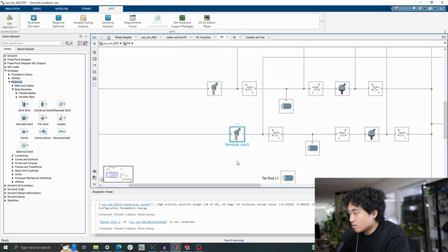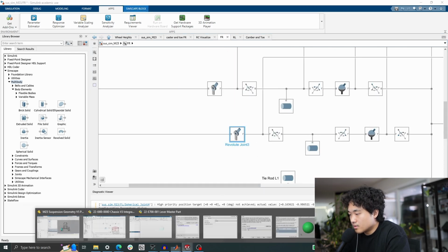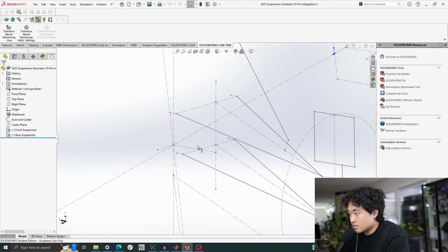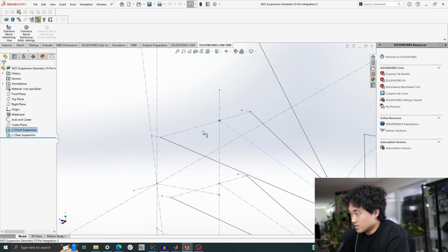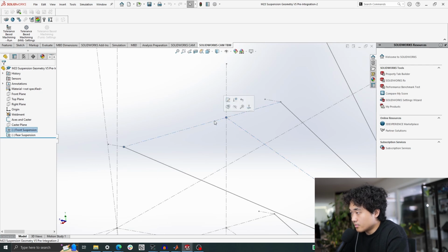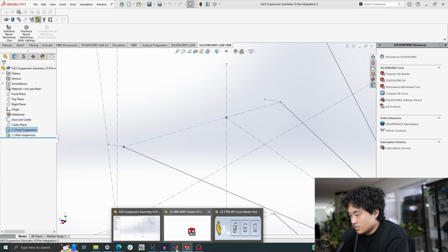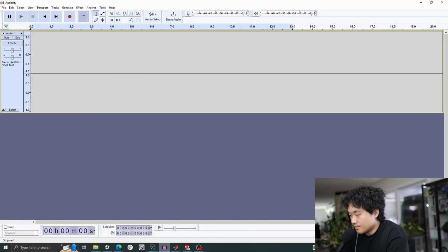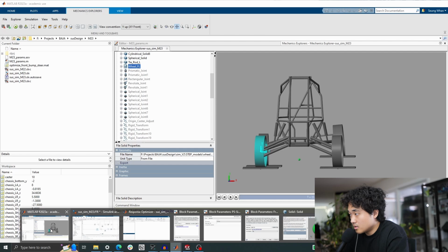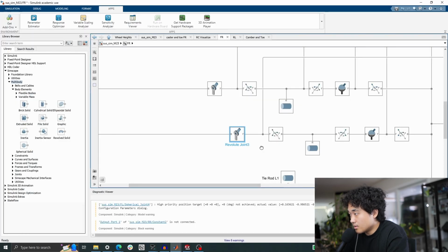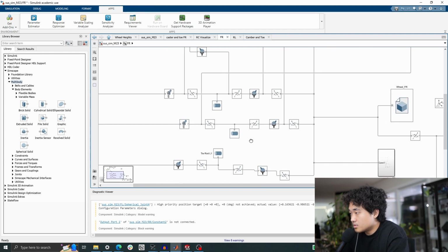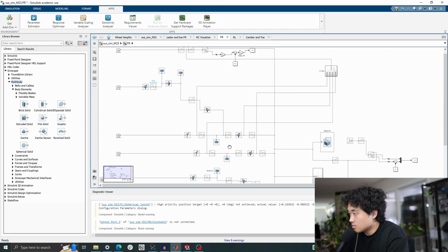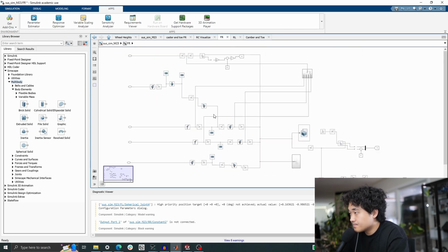For example, in real life, this is more like two spherical joints, right? So one here, but we're modeling just virtual A-arms for the sake of some simplicity. So we could just say along this line, it's a revolute joint, meaning just simple one axis of rotation for its DOF. There you go. That's how you define joints and where the joints are located with respect to two parts.